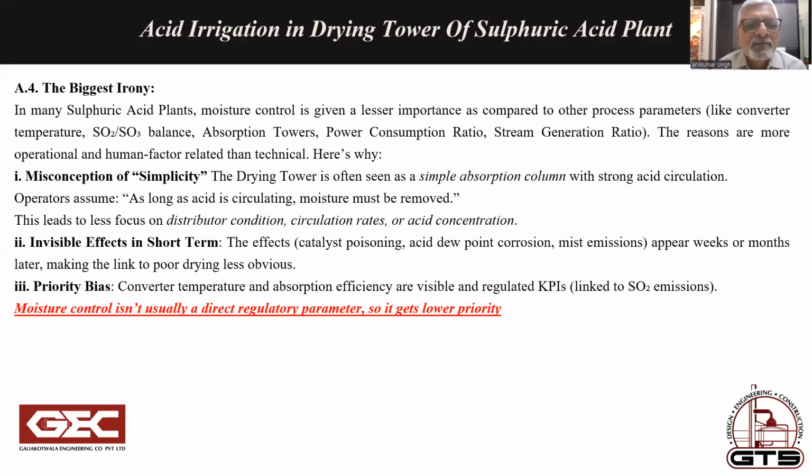Priority basis. Converter temperature and absorption efficiency are visible and regulated KPIs linked to SO2 emissions. Moisture control isn't usually a direct regulatory parameter, so it gets lower priority.